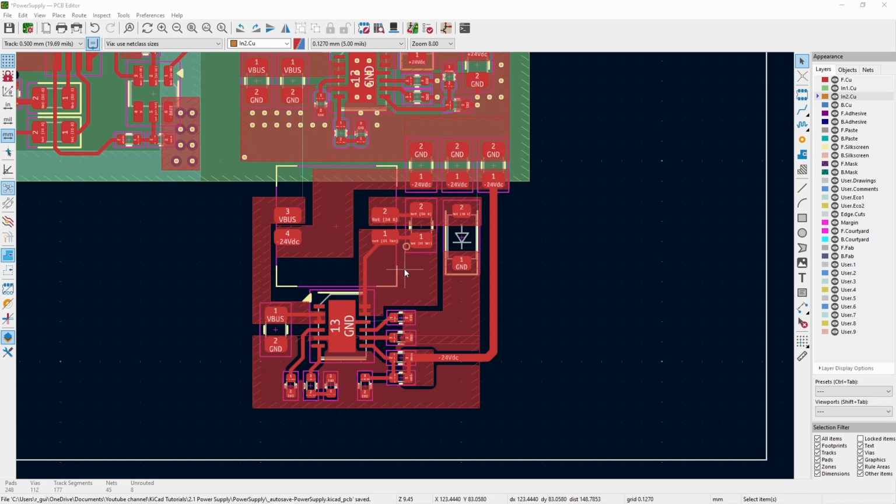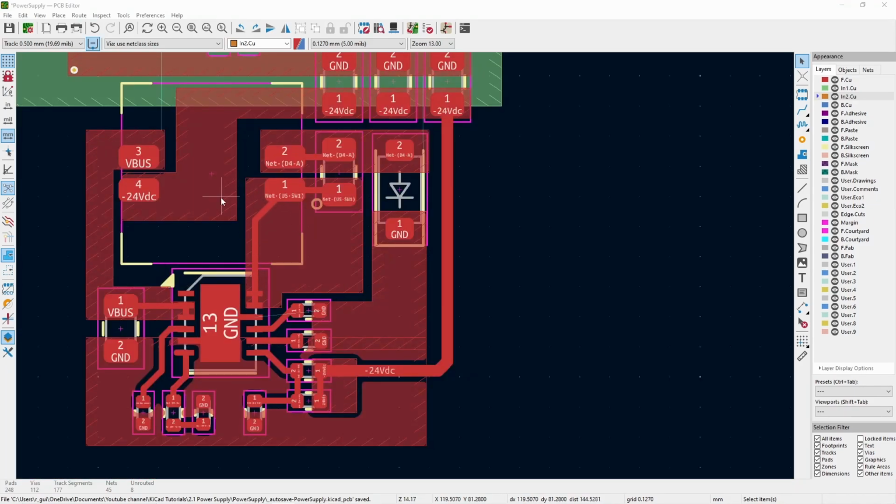So I've done the PCB design. I'm a little bit unsure about the feedback track that's going from here to here. I'm considering if I should run it from here, but obviously that's going right under the switching node, which is high, which may have a lot of noise.